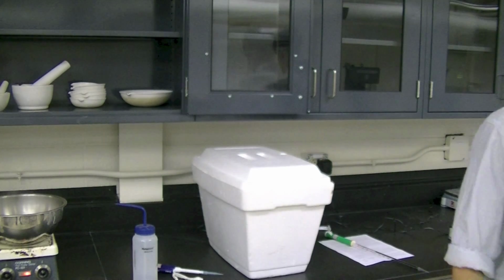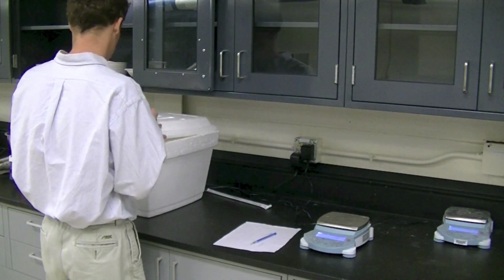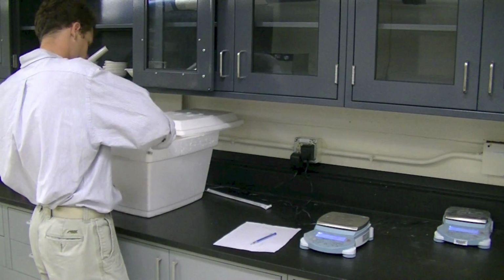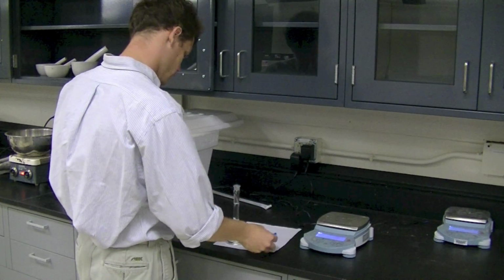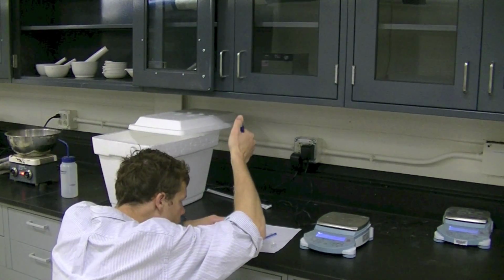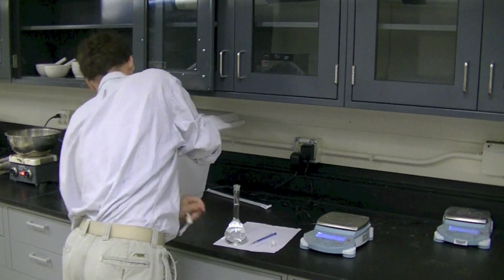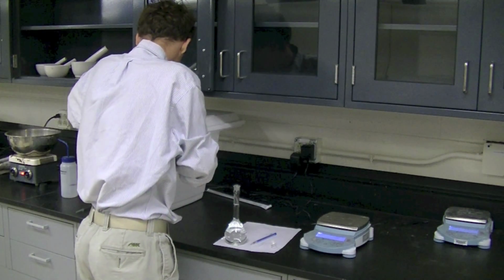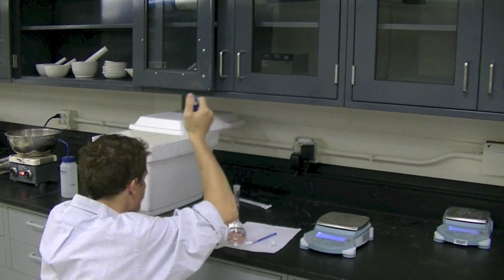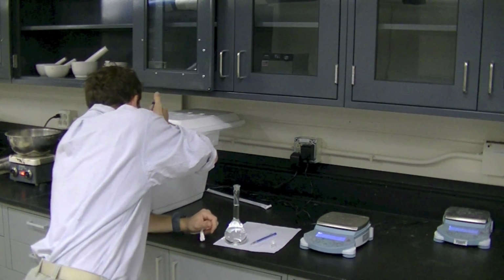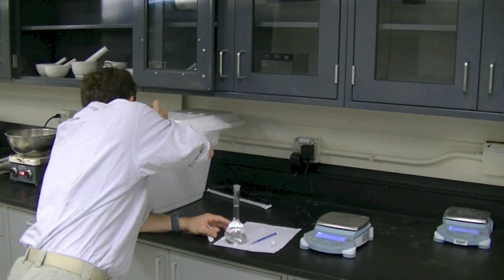After at least 3 hours, remove the pycnometer from the insulated container, being sure to handle the pycnometer by the top. Adjust the water level to the calibration mark so that the bottom of the meniscus is at the calibration mark. Be sure to use water that was stored in the insulated container to reduce temperature changes. Use a pipette or eyedropper to add water. Use a pipette or paper towel to remove water.